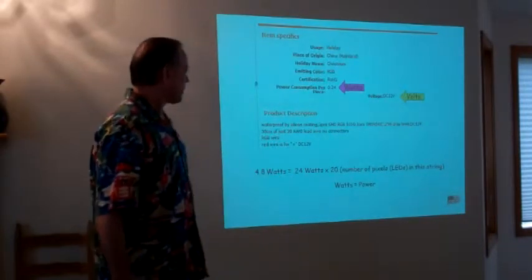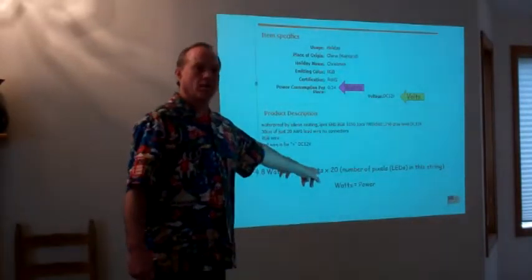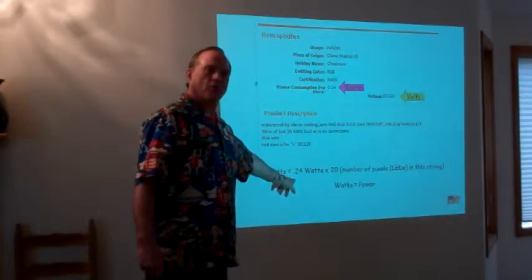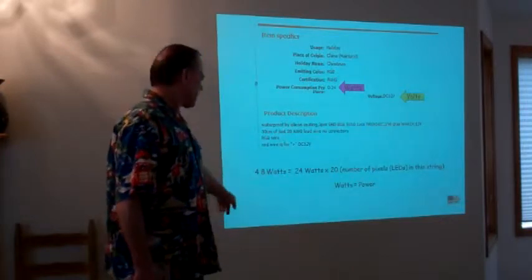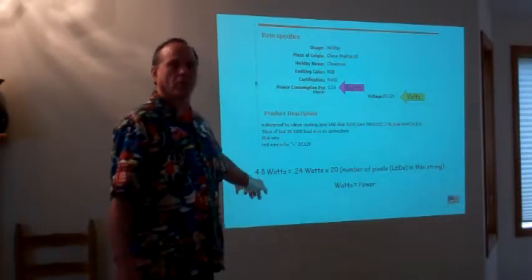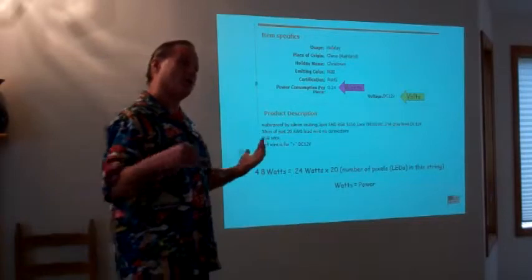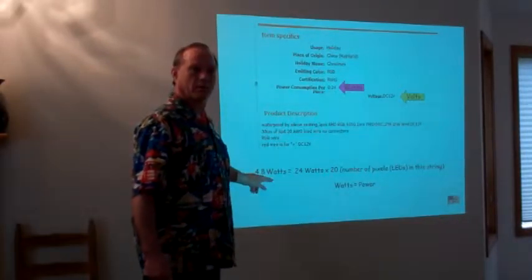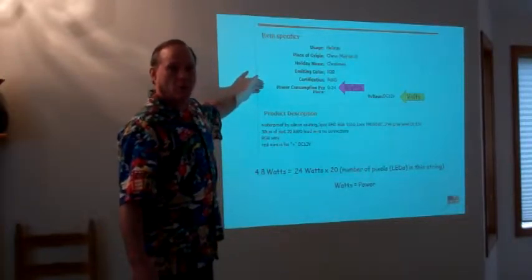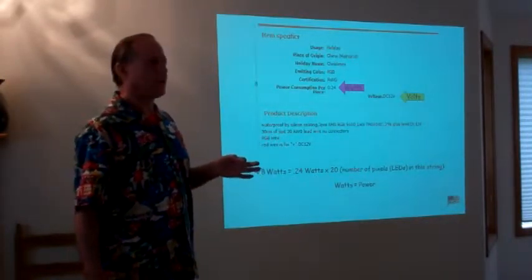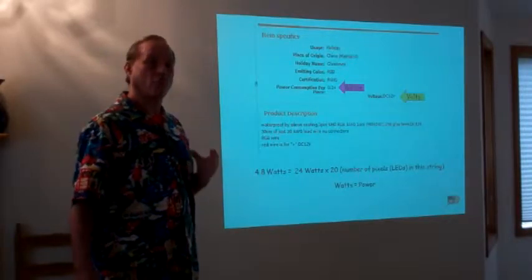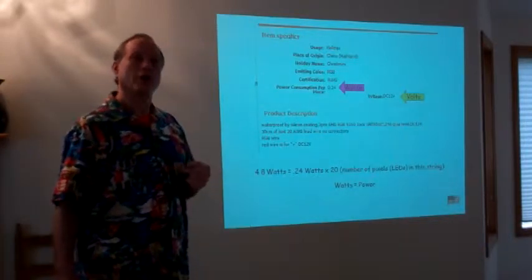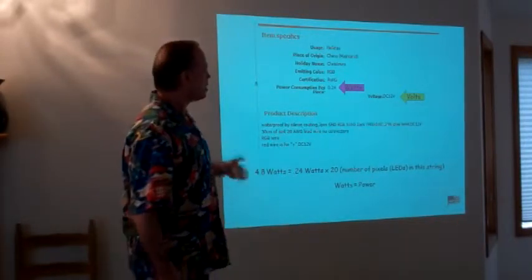So for that string, again, we've got 20 of those 50/50s, the squares. They require 0.24 watts, so 20 times 0.24 is 4.8 watts. Now if I was going to utilize both of those strings together, I would be adding this amount to the previous amount, because watts is all we're really concerned with, because our power supplies are going to need to deliver us watts. So when we add these up, we will have the total number of watts that we need for our load.